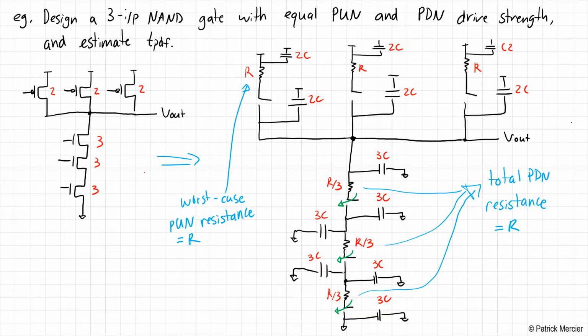Now you might say, well, we actually need to know the status of what these switches were to know what the pre-charged voltages of these internal nodes were equal to in order to analyze this circuit. And you're absolutely correct. We're going to, for the moment, ignore that, and let's just assume all of these capacitors were originally pre-charged to VDD, and we have to discharge all of them.